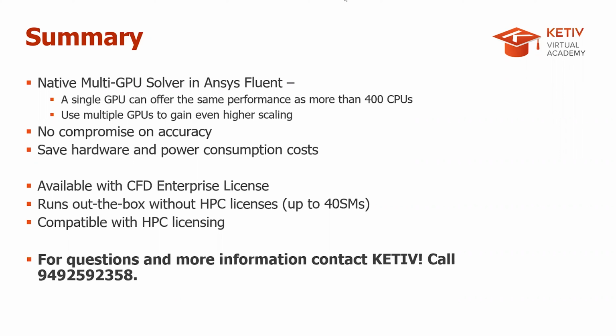If you guys already have Ansys Fluent on your machines, you might want to just launch the GPU solver in the beta mode and try to do an internal flow or a conjugate heat transfer problem. See what type of speed up you're gaining by switching to the GPU solver. I'm sure you guys already have GPU cards on your machines, so you can always see if you're getting any advantage from switching to the GPU solver and see how the UI is different from the conventional CPU-based method. It's not very different. It's just a matter of which models are available in the current particular release.